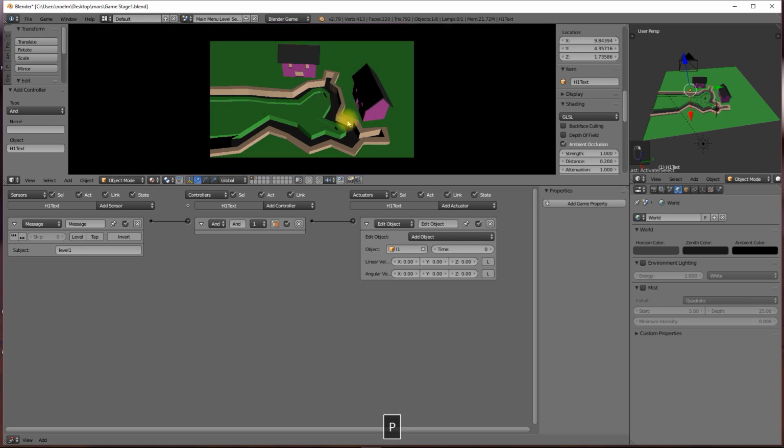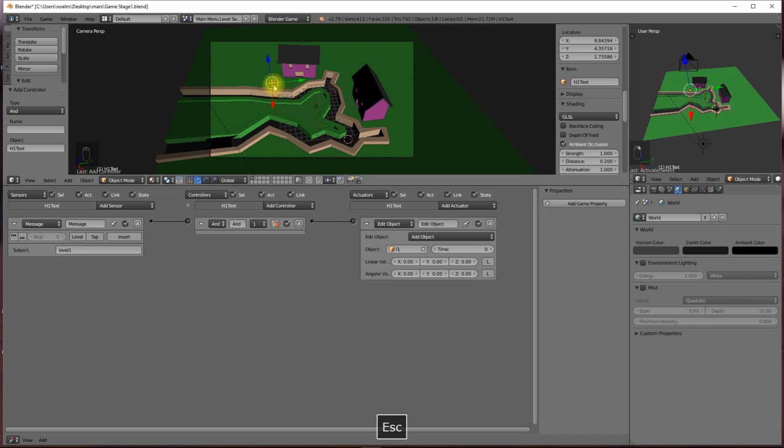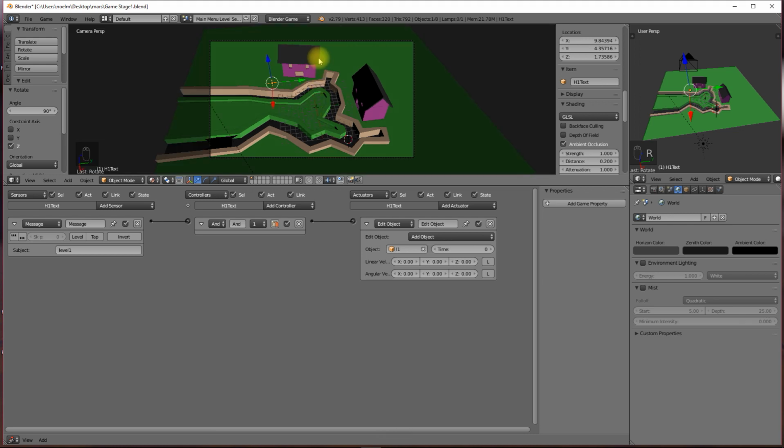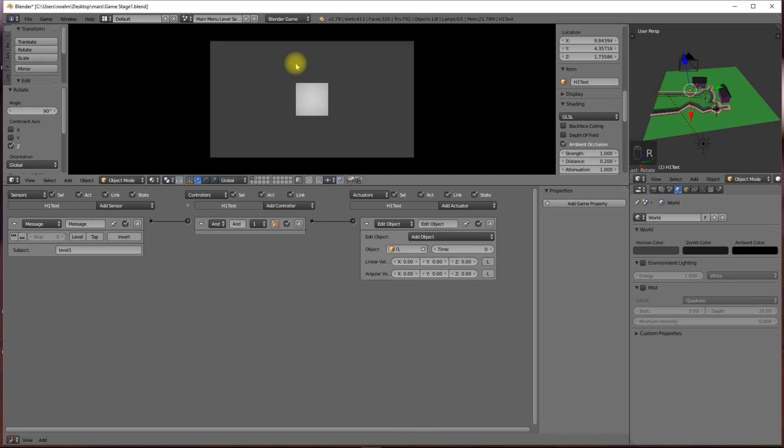So let's press P. The mouse is visible. I put the mouse over here, and I've got L1 coming in, but it's facing that way. Okay, so let's take this empty and rotate it on Z 90 degrees. So R, Z, 90, and now see what we get. So P, mouse over, and much better. Level 1 is not perfect, it's overlapping the house a bit, but we can live with that. So I can click on it and change level.